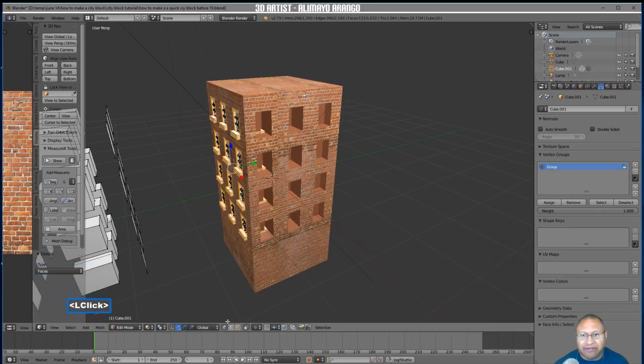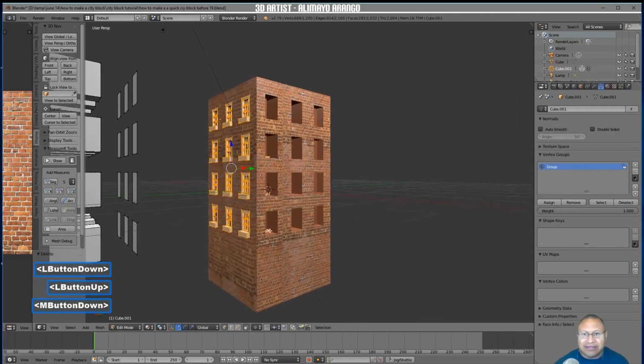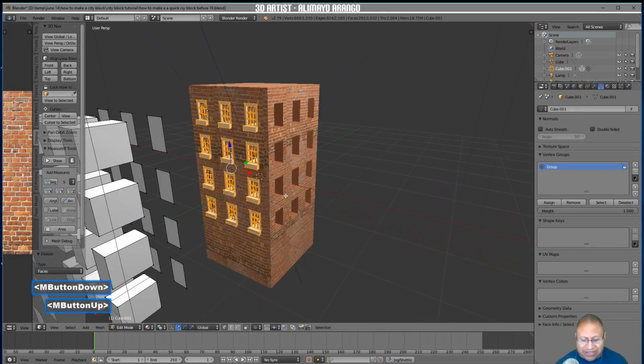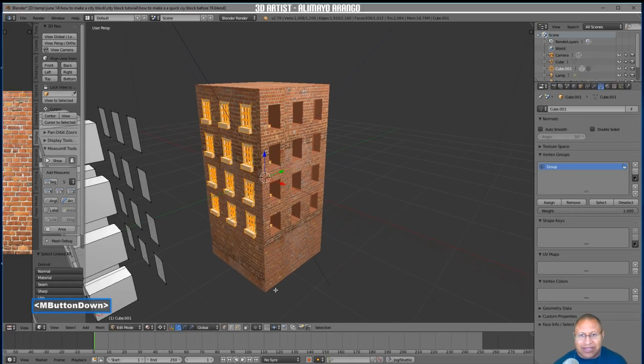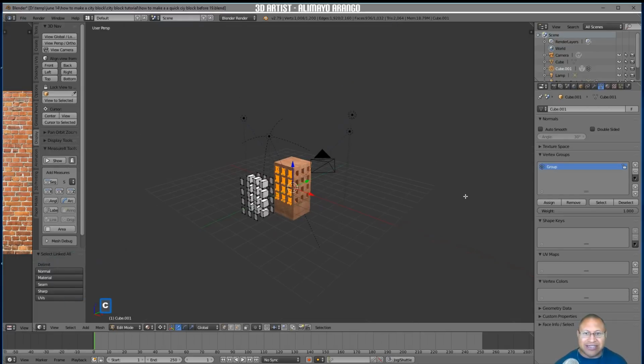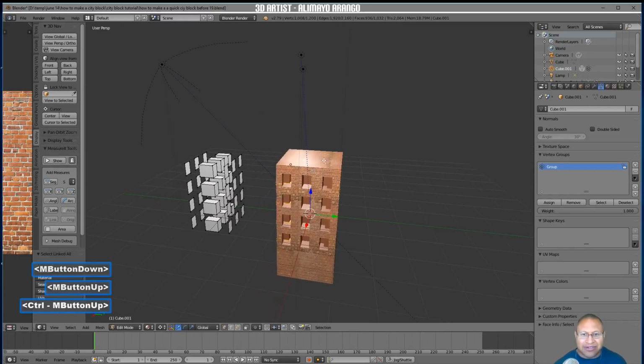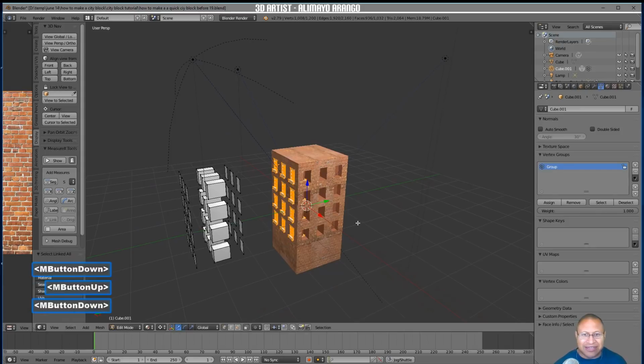I'm going to go to vertex select. I'm going to press B, and as long as you grab some of this geometry, you can hold Control, press L. We have our 3D cursor here in the center, so I'm going to click here. I'm going to select 3D cursor. And if I right click here, see the 3D cursor is away. Now I can hold Shift C, and then the 3D cursor is right back in the center again.